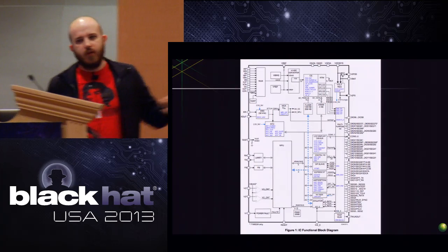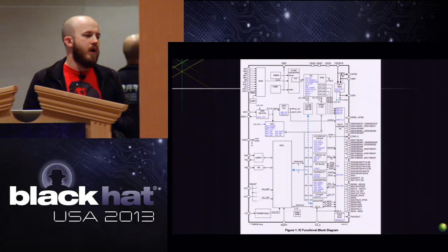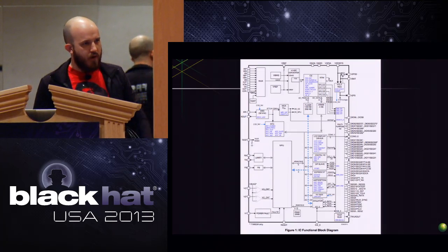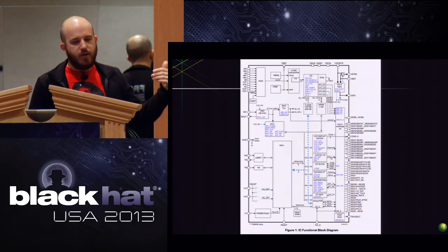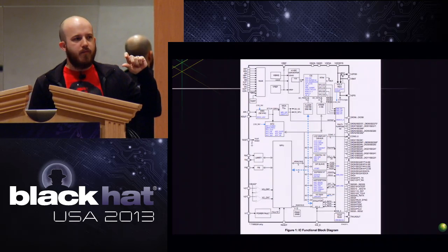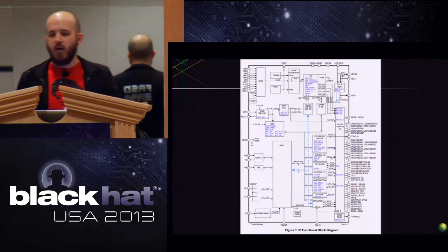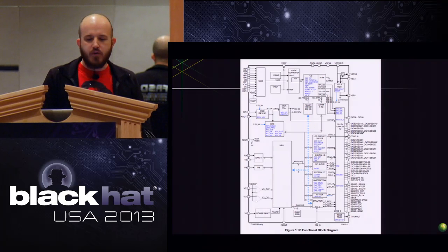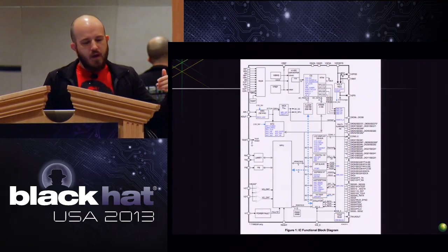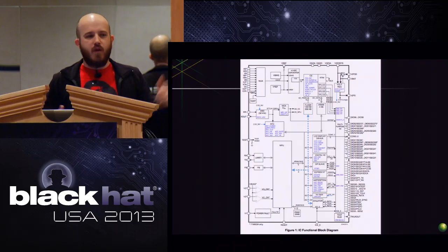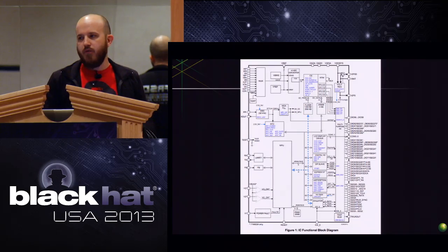So it's got stuff to drive the LCD screen. It's got stuff to drive the pin pad that's on there. It has lots of inputs that are designed specifically for measuring power usage in an accurate manner for smart meters, right? Every single SoC, all the Teridian SoCs, have a very similar structure. They've got an 8051 core, they've got memory, and then they've got different peripherals that they stuffed in for the different use cases.